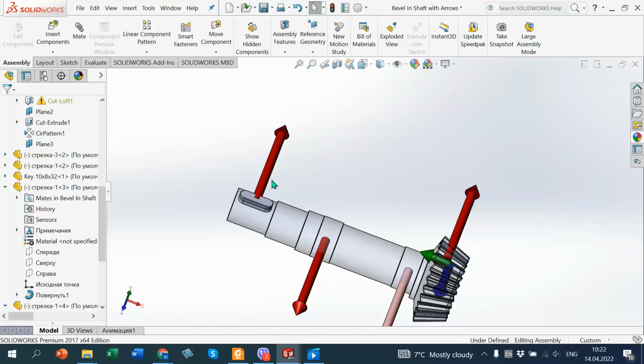We don't know where, what is this direction. That's why we use direction which creates the highest load for bearings. If we direct this force at the same direction like biggest force in gear transfer, we have the maximum load on bearings.